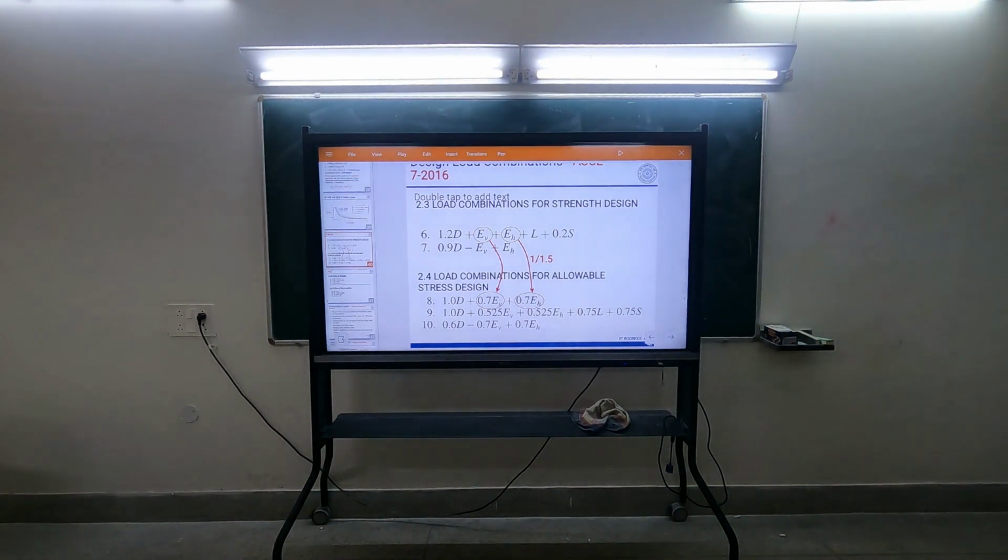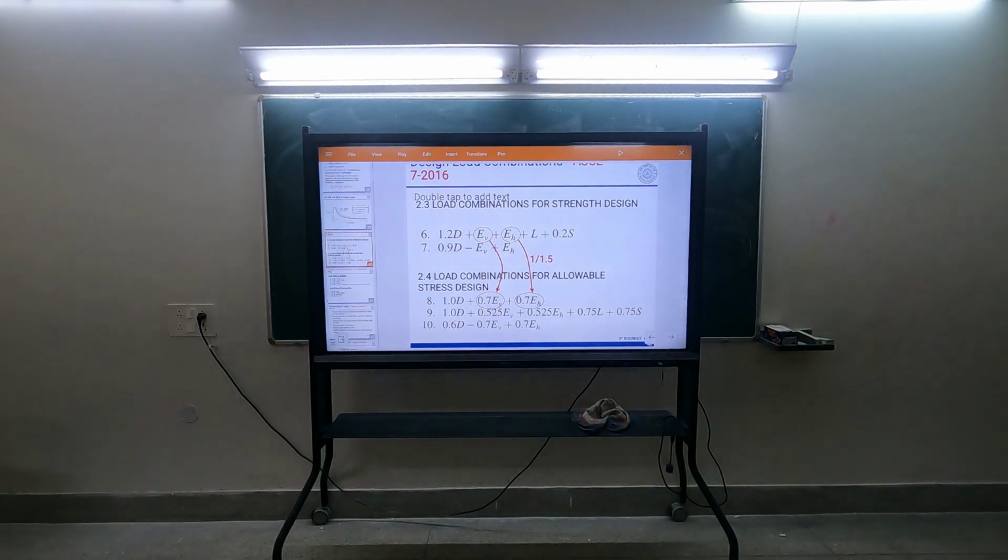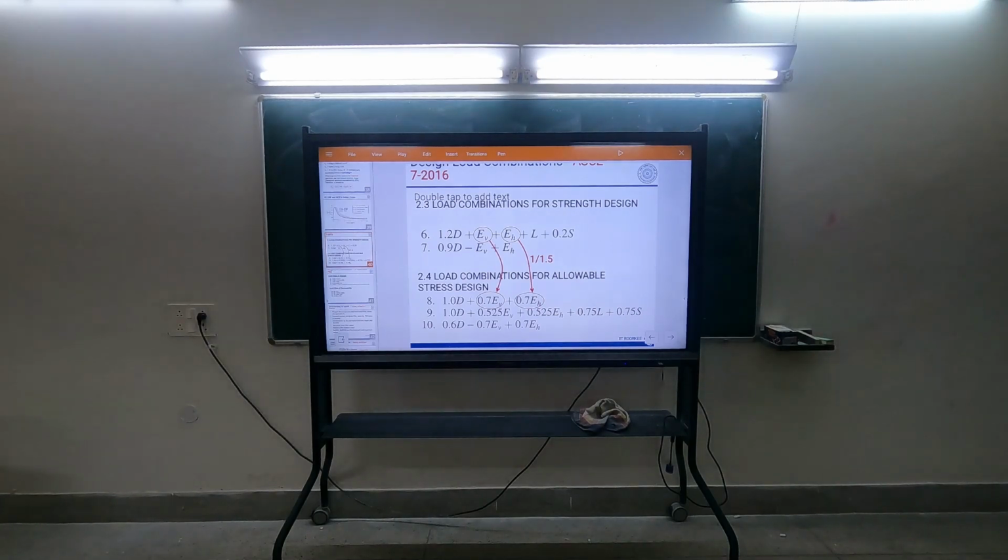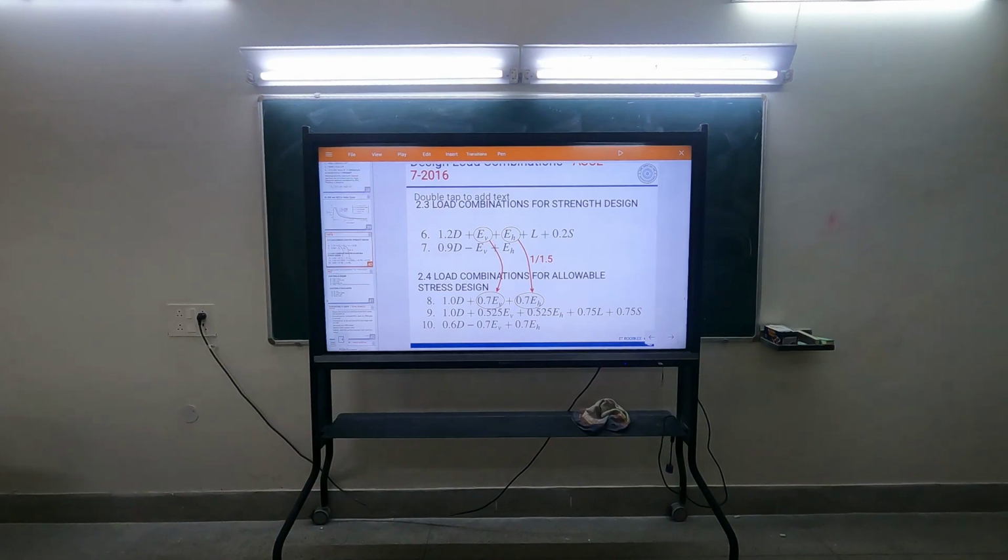We are using partial factors of safety. We have used a factor of safety of 1.5 on concrete. In case of a beam, concrete does not govern the strength, because usually we will be designing under-reinforced, and steel will be governing the strength. So we have applied a partial factor of safety on steel also, and the actual strength is higher. In steel, when you calculate Fy, it is also not mean strength, it is also characteristic strength. So that will also have a higher strength, plus 1.64 sigma.